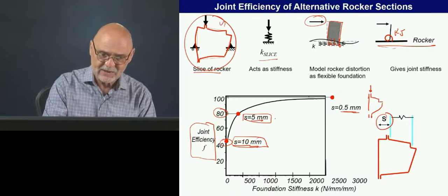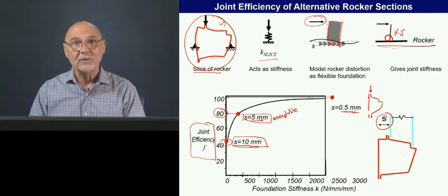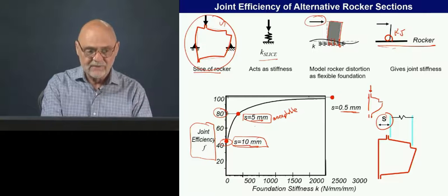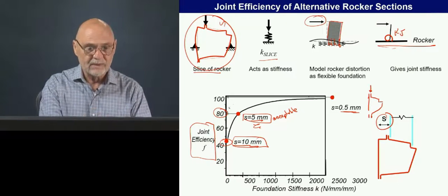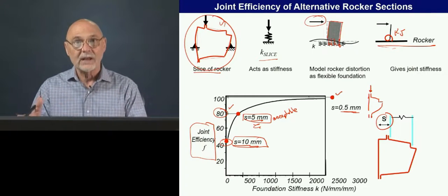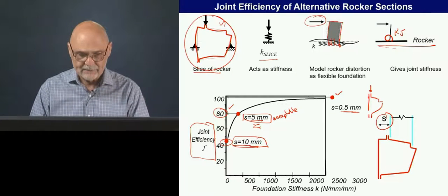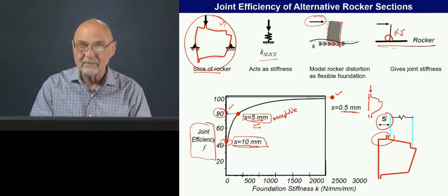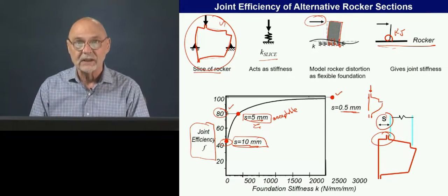We could say this might be acceptable from a structural standpoint. We know that there are some reasons to do these kinds of things. If we could achieve 5 millimeters of maximum offset, that would be relatively good. We can do better than that if we zero it out, but maybe that's a point of diminishing returns. So this is an idea of the relevance of even these little details in how these joints come together.